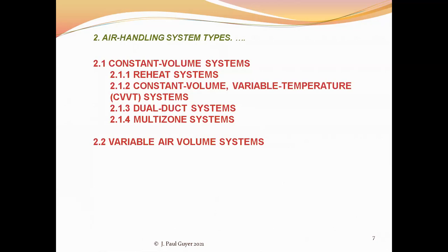The other approach with multi-zone systems is that you can have a little tiny coil, so to speak, in each one of these 10 ducts, or zones, that take off. And so the thermostat in each one of these zones tells the control valve on its coil to open up and provide more refrigerant or chilled water to its little coil.